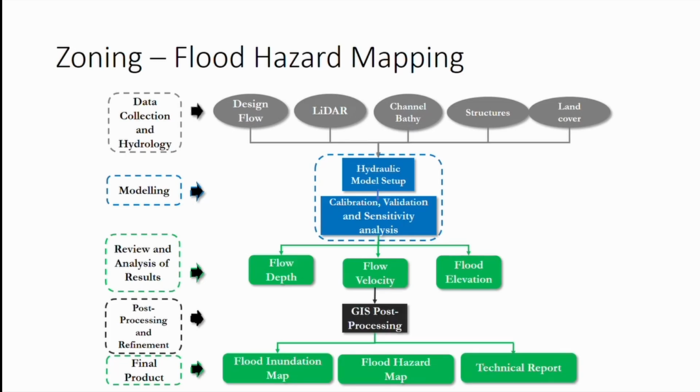When the model is looking at it in one direction, what are called 1D models, we can use solvers such as the standard step approach, which only solves the equation in one direction. But if we are interested in a two-dimensional way of looking at the floodplain, which is more realistic, then the shallow water equations are approximated with a number of schemes.